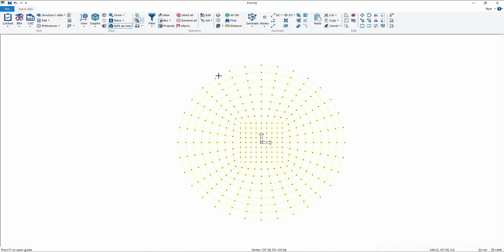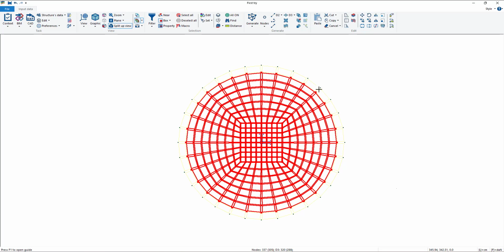Now we need a bit of patience, because it's hard to select circularly. No, in reality we have a command, it's box circle. We can select circles, so we can go like this. Let's say that we want to select only this, because the external one is 50 centimeter, it's already right. We want a second one, so what we can do is right click, display isolate, so we are hiding the external one.